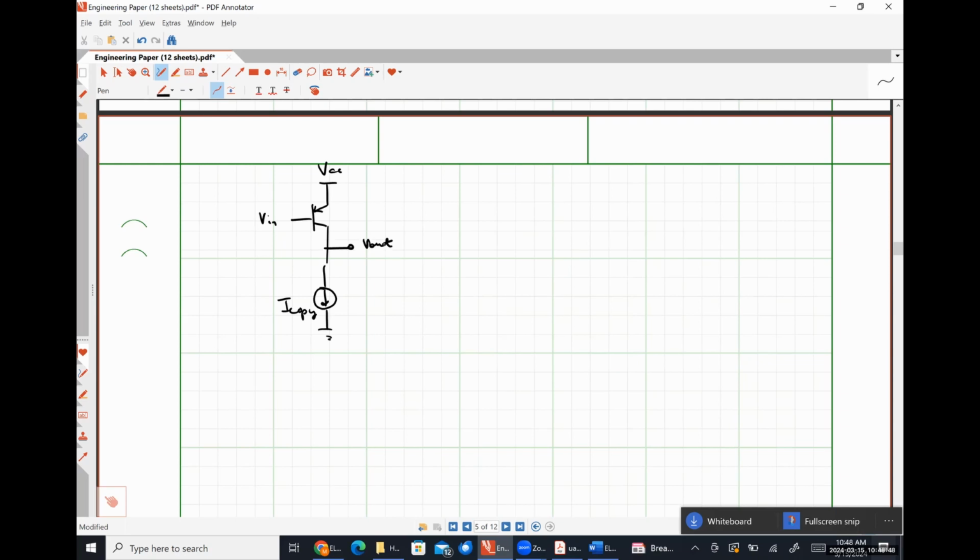What we're going to see in a little bit is we can change this to give us a current on the top side by connecting our NPN current mirror to a PNP current mirror. And then that will move the current source above. You can't just draw a funny wire like this. No. And guess what? Adding the extra current mirror, of course, introduces more error. All right, thank you.